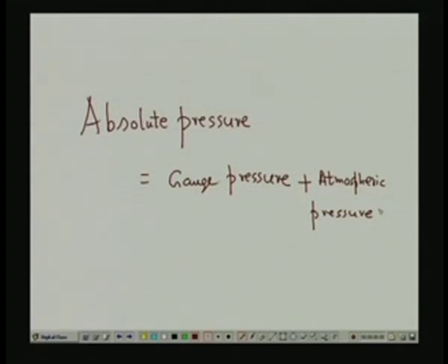Typically this U-tube manometer looks like the English letter U, and that is the name we have coined for it. I should say it is one of the oldest pressure measuring devices mankind has developed. Still it is used as a monitoring instrument in many process industries, for estimating pressures in bioreactors, in the laminar hood or in the actual process. It also has a wide range.